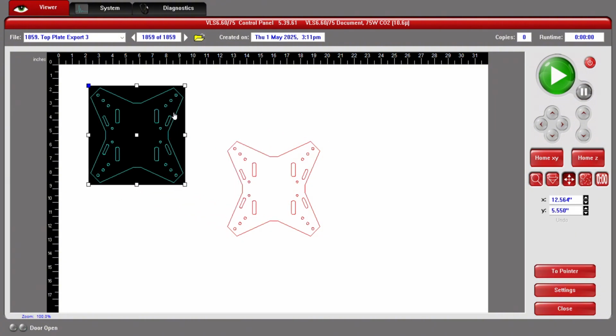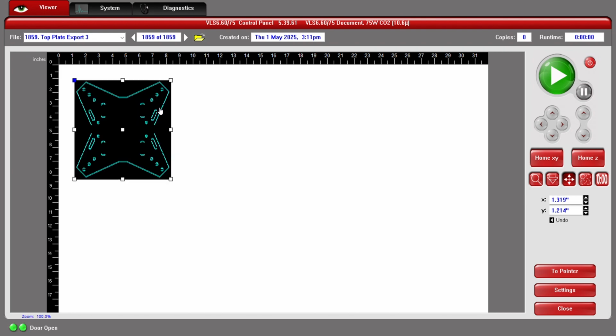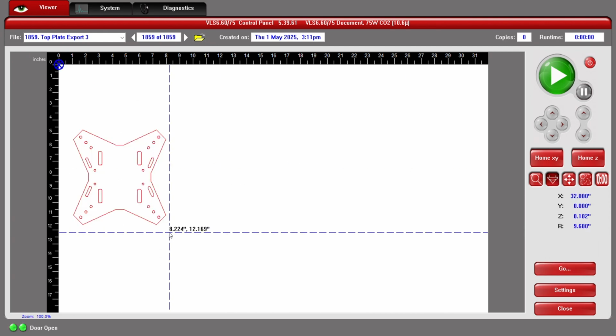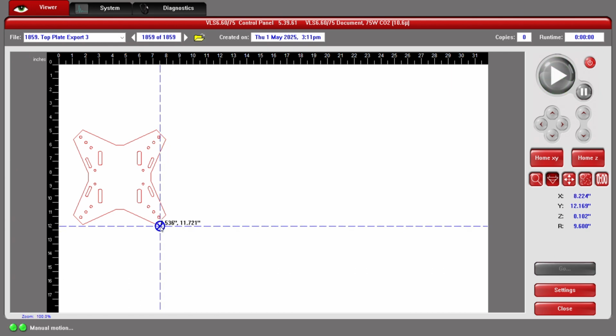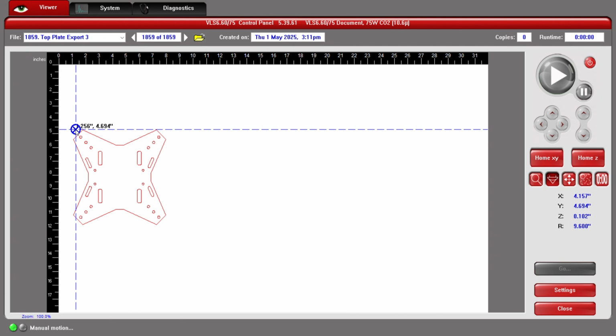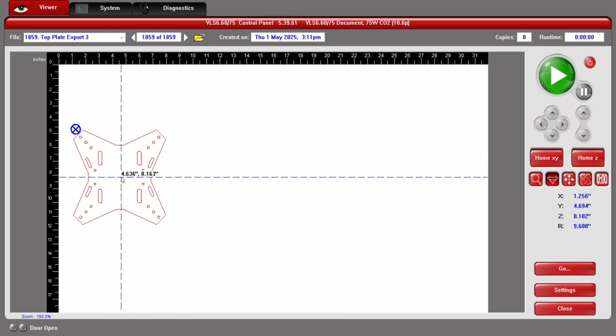After the part is imported into the laser cutting software, we can use the Move tool indicated by the 4 arrows button to move the part anywhere we want on the cutting plane of the laser cutter. To ensure the part is fully on the material, we can use the tool with the laser head icon to physically move the laser head to a position on the build plane of the laser cutter. Using this tool, we can check the most distant points of the part to make sure it fully fits on the material. The laser head will display a red laser dot when the lid is open. This will allow us to see where the part will be located and physically cut out.